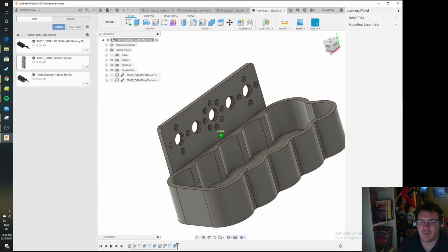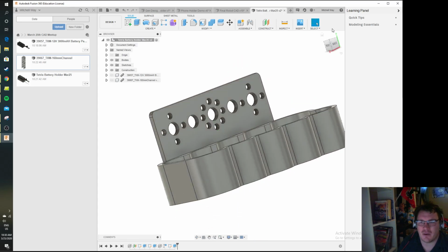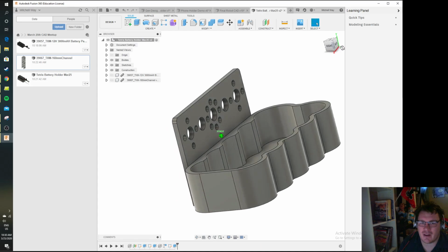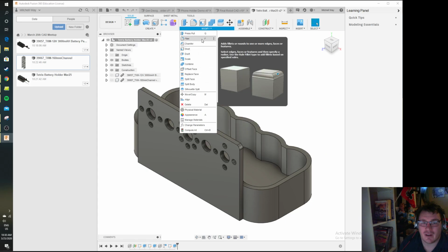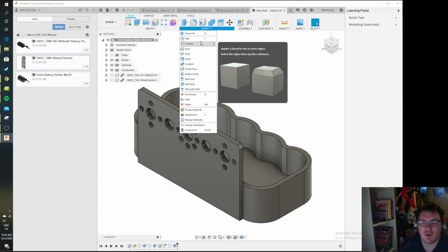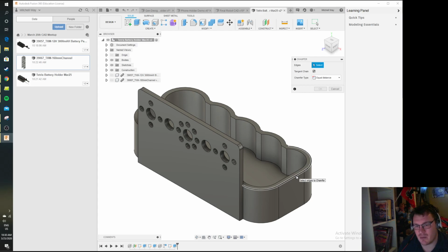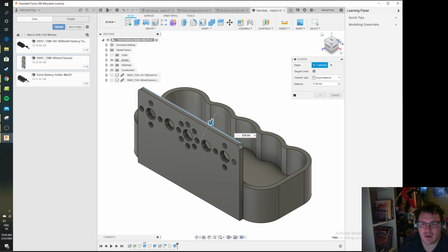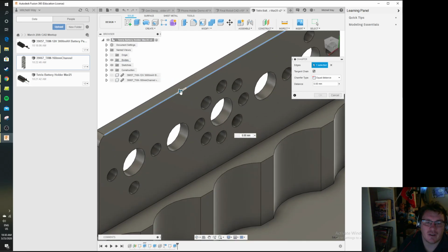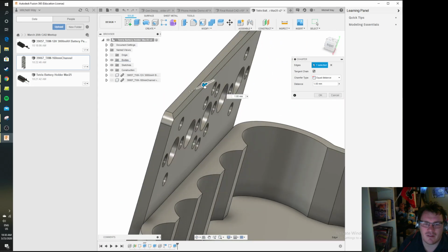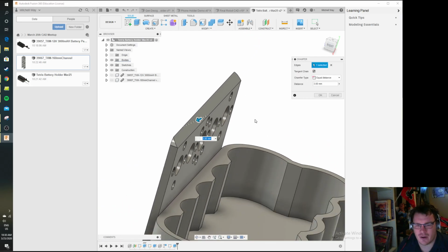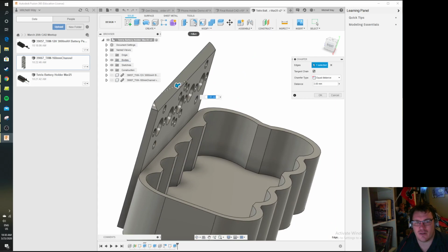I'm going to show you one more thing here. I've got one more task we can work with, because if you want to make a few more fancy things, you do have some modify tools that are somewhat powerful here. Okay, one of those things is fillet and chamfer. If, let's say, we decided we wanted to actually cut off some of the edges here and actually smooth this down, we also have that option to do this in 3D once we get to this part. So I'm just going to put, I believe this is a chamfer. You'll notice that this is going to cut off an angled version of that particular piece. If we, say, wanted to remove some material or wanted to create an angled edge, we have that option. Fillet's going to create a rounded edge.